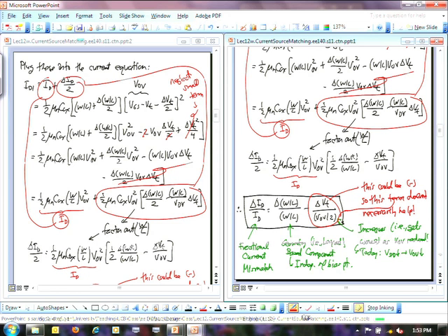Right, so first of all, what about the concept of an ideal voltage amplifier? So what does ideal mean to you? So it's ideal when your gain from your source voltage Vs to your output voltage V naught is equal to A sub V. Okay? And so, in other words, it's ideal when the source and load resistors cannot influence the gain of the amplifier. That's a definition of an ideal voltage amplifier.